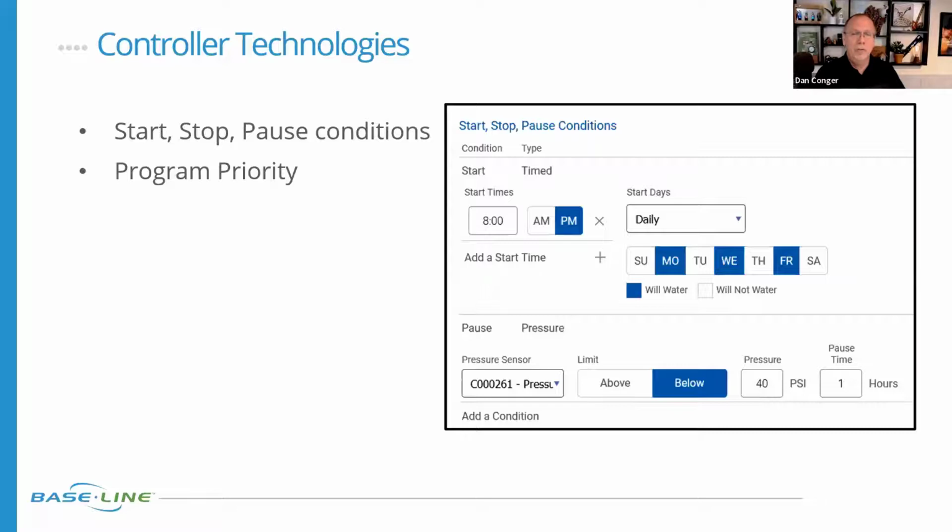When the pressure drops to 40, that DU just goes to crap, right? And this is like, well, why waste that? Why get the donuts? Let's just wait till the pressure comes back up at the right time of day. I'm not going to waste that water and get more bang for my buck out of that water, so to speak. That's right. And I think we've discussed on a previous episode of Tech Talk Tuesday that a 10% difference in pressure can have a 40% impact on the amount of water that's used to irrigate an area, right? Nice. So managing that, monitoring it closely can also contribute significantly to your water management program.